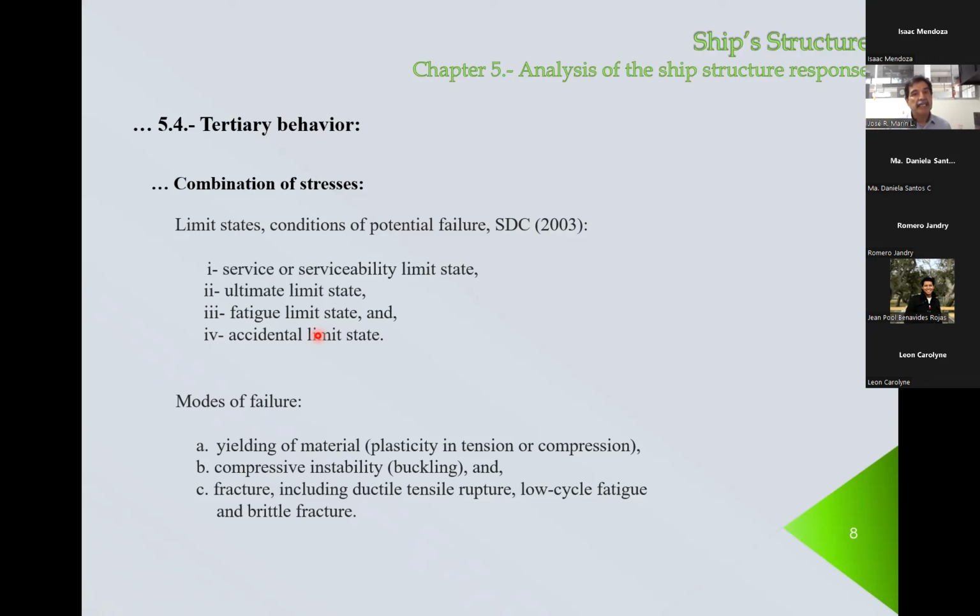The other possibility is buckling. Every time you have something like this in compression, the non-deformed position is unstable. That means that the structure will try to get away from that situation because it is unstable. It's like having a little hill and you put a ball on the crest of this hill. You just blow a little bit and the ball will roll away from that situation, because this is a static equilibrium, but it is unstable.